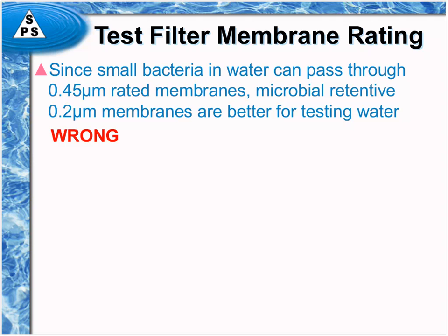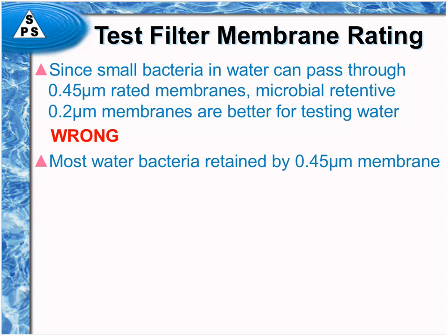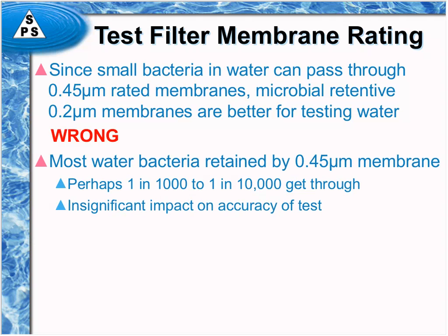That's wrong. Millipore actually did a study, and they didn't even use water organisms. They used a battery of challenge organisms. And the way it turns out is that 0.45 micron membranes will actually allow some percentage of all kinds of bacteria to get through. But it only allows maybe 1 in 1,000 to maybe 1 in 10,000 of the organisms to actually get through, which is certainly not exclusive enough for a 0.45 to be used as a sterilizing grade